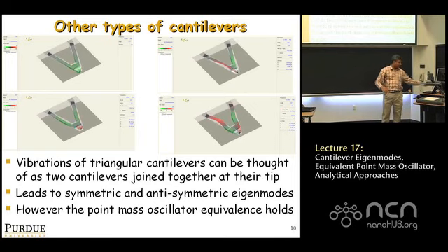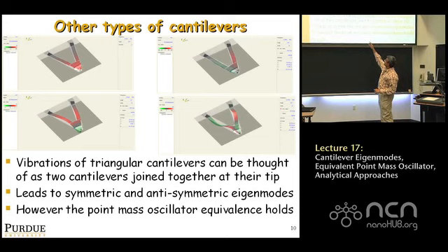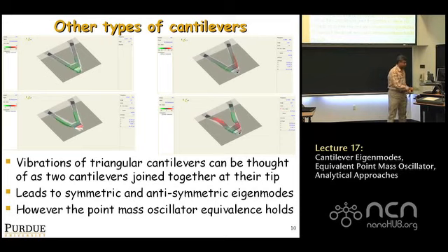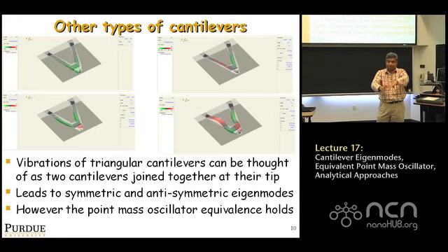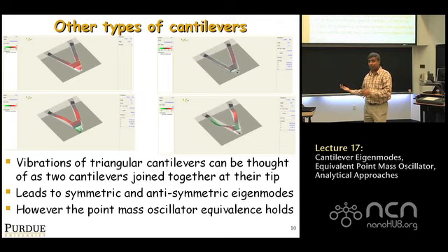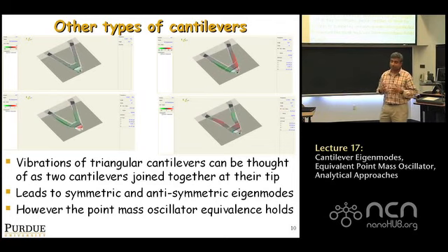Then you look at this one at the bottom left, and there's a second mode. And just like there's a second mode, there's an out of phase second mode. This is where both beams are oscillating in the second mode, but out of phase, causing a twisting-like motion. And even this frequency is different. It's not the same frequency relationship as we had.